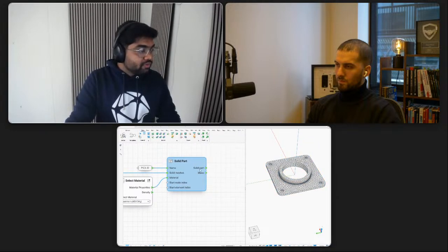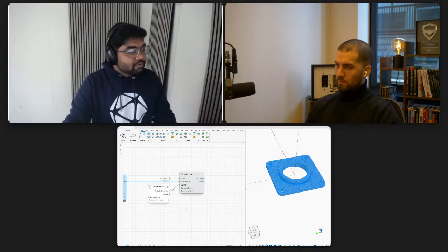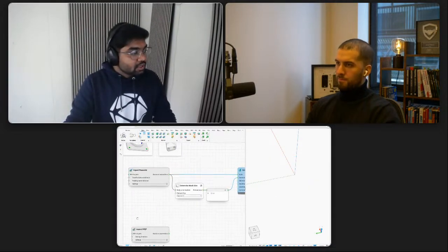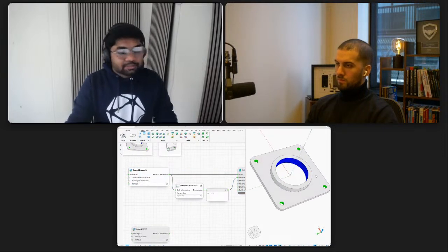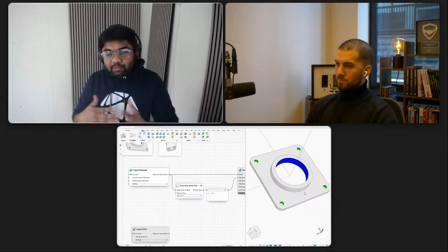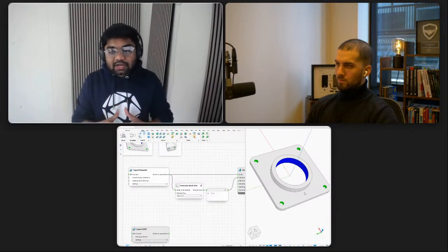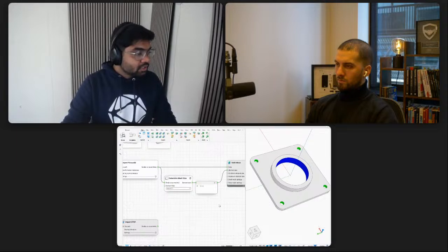And then, we are good with the mesh and assigning the properties. So the next step is assigning the boundary conditions. As you observed, this given geometry has metadata, that means these color attributes. This is like a communication between a CAD engineer and a simulation engineer, on how one can assign the boundary conditions, which is force and fixed displacement.